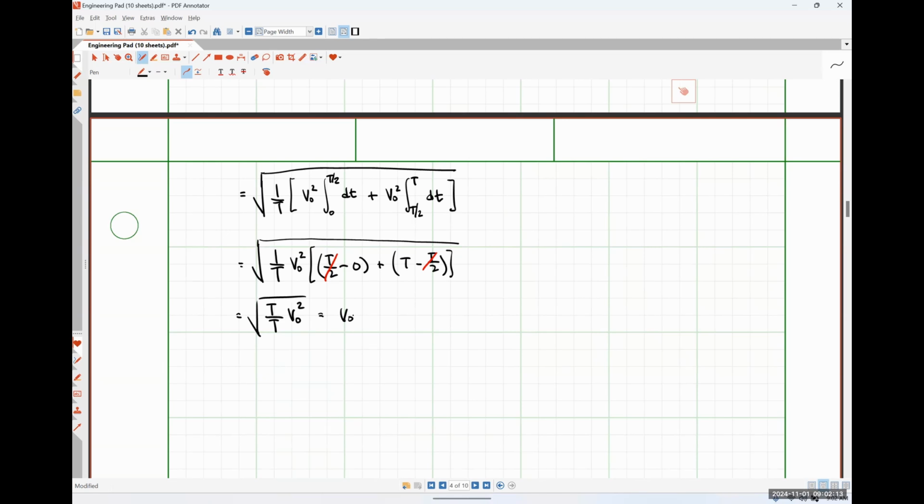So for a square wave with a 50% duty cycle, meaning that exactly half of the time it's low and half of the time it's high, it's literally delivering the exact same amount of power as just a constant DC of its maximum. And you guys literally worked an example showing that on your first homework set in this class.